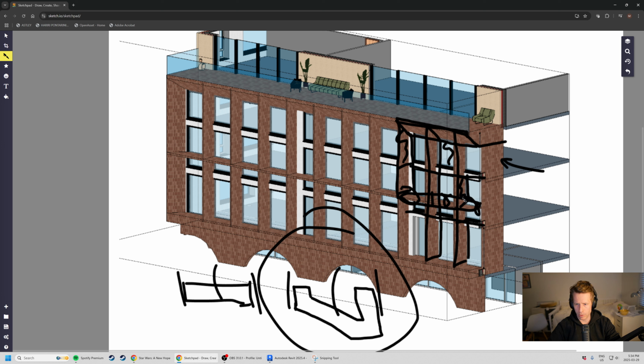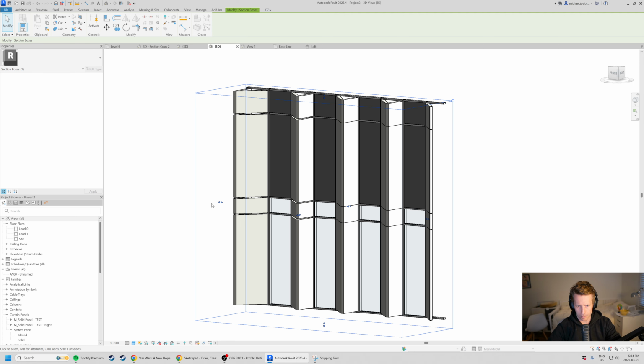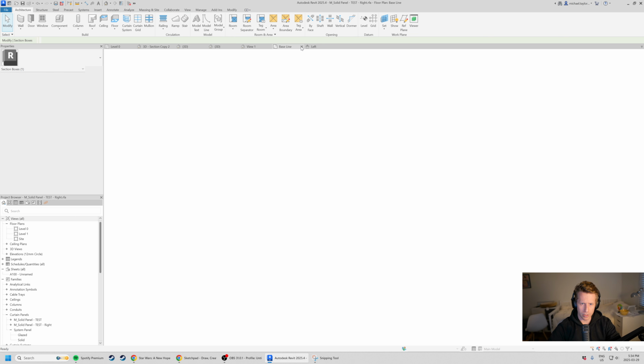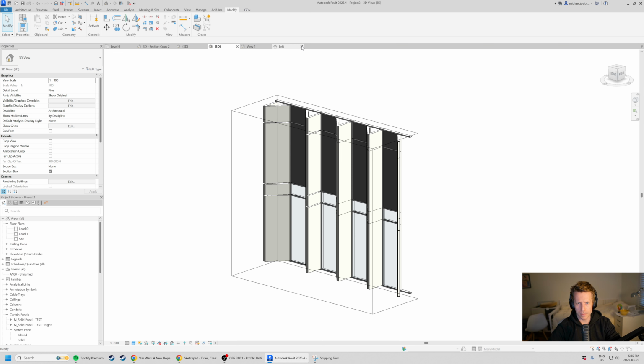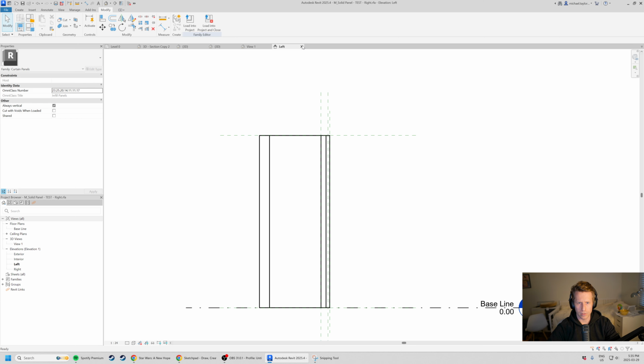So similarly, we've got vertical, vertical, vertical. And then what we want to do is build a piece that's going to come across the horizontal panels inside of Revit. So we want them to come this way. So very similarly, I'm actually going to just jump back into our family. Is this open? Yeah, this is open. That's okay. Close this.